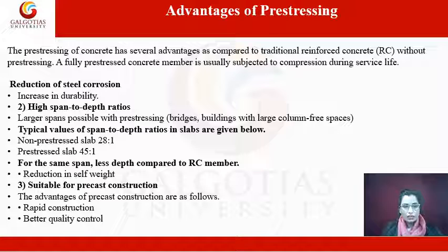Second is the high span to depth ratio. If we use the pre-stressing method, large spans are possible, like bridges and buildings with large column-free spaces. So in these cases we can use the pre-stressing method.